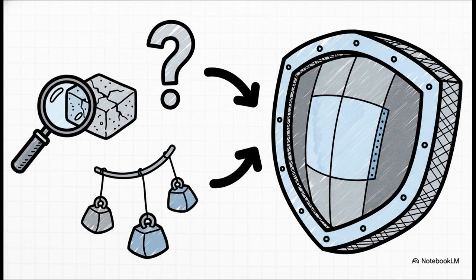How reliable are your material properties? Do you know exactly what the applied load is going to be? What's the certainty of the exact mode of failure? Basically, the less certain you are about any of these factors, the higher your factor of safety needs to be to compensate.